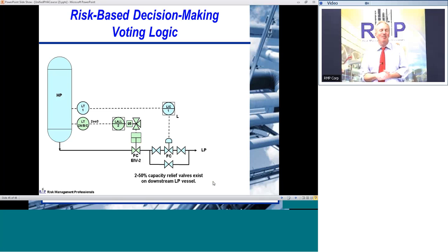What is the likelihood of level control valve 1 opening? So pulling those together can help make decisions on how much redundancy you might want in your sensors. And I have to tell you that a lot of people tend to over-apply multiple sensors in voting logic. You really need to think about a couple of options. Let me talk about them.